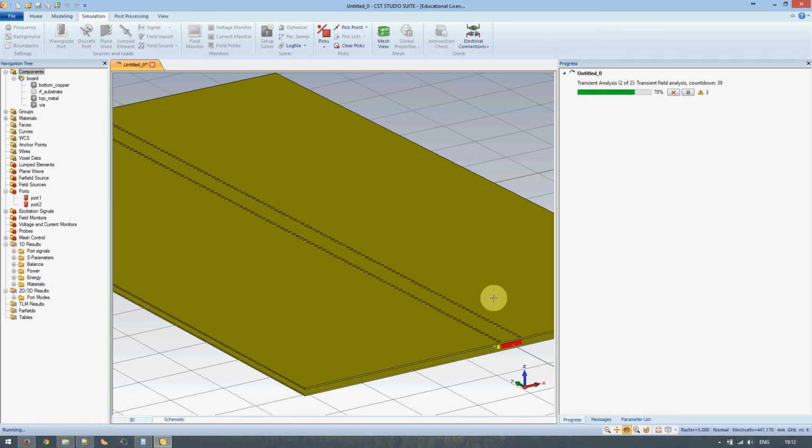Frequency domain solver uses a phasor-based technique, but it has to do many frequency samples. So particularly if you're doing wideband applications and non-resonant kind of stuff, it does take longer, and it is better to use the transient solver. And if you want to obviously verify the response of your waveguide structures over the cutoff region, you should use the frequency domain solver.